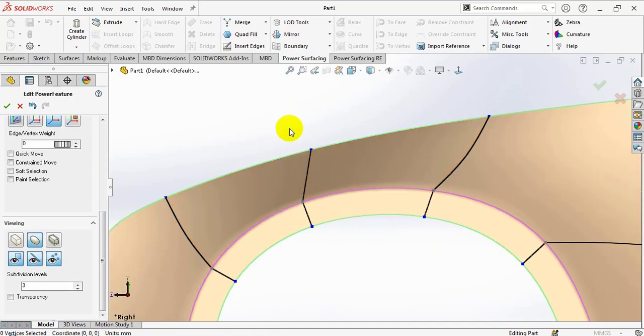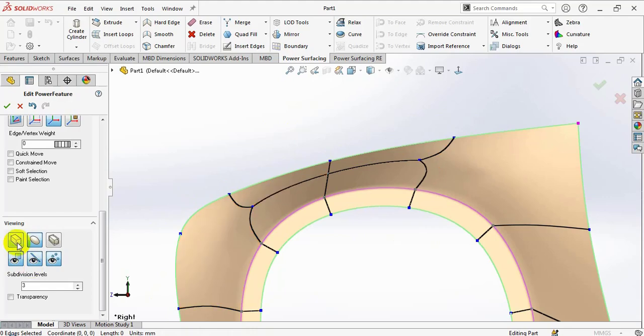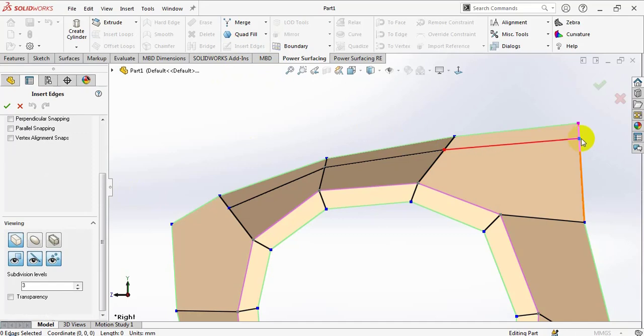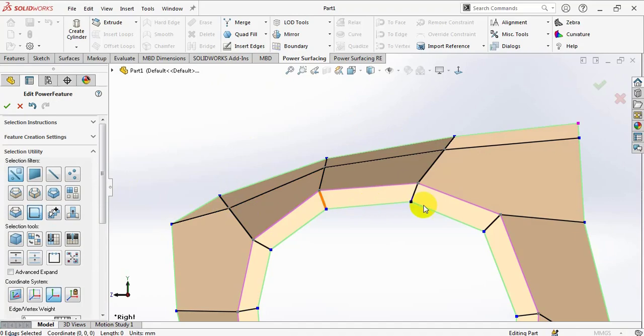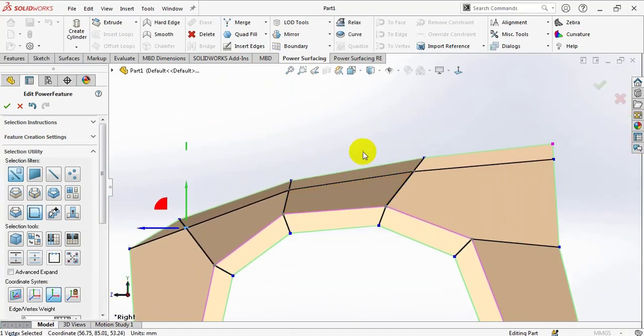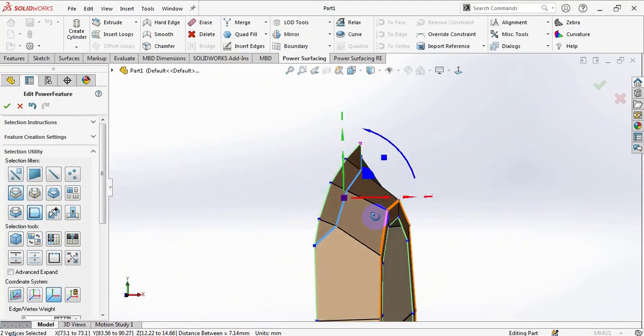So I'm gonna create an edge loop by holding the A key. It may not make it to the end because here there's no other line it can snap into, so we can just convert it to this view and insert edges, you can just add it manually. Click and click here and just make some modifications. Okay, we can just select the edge loop again, selecting this here and making this view.